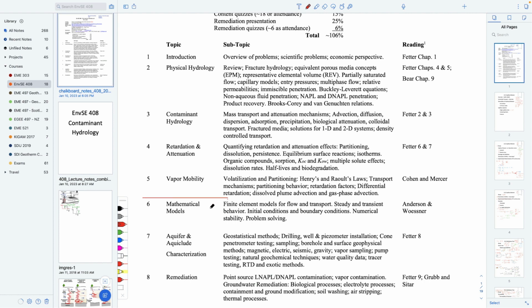So what we've covered is everything in the vadose zone in terms of free phase transport. Motion is constrained by interfacial forces. Ability to understand that behavior in terms of capillary pressure versus saturation curves and relative permeability magnitudes. Getting into the groundwater saturated zone, transport by advection and dispersion, understanding controls of that by sorption and retardation, what that means in terms of rates of transport, and we've now just applied that to understand how behavior occurs in the vadose zone, which follows on directly from that.